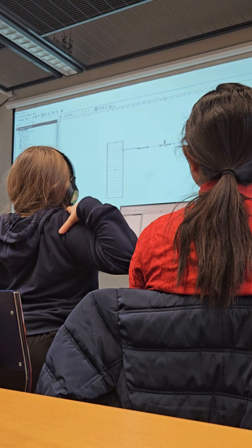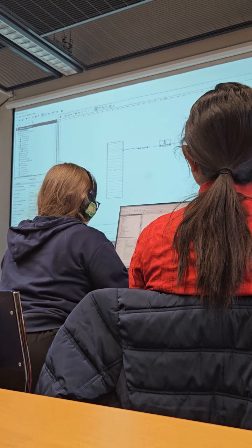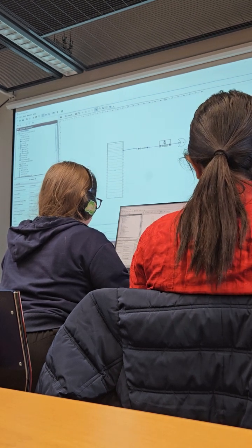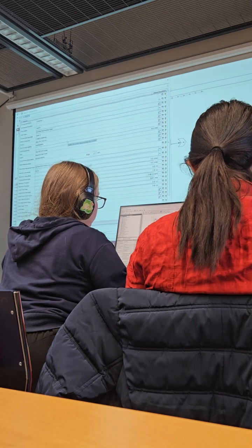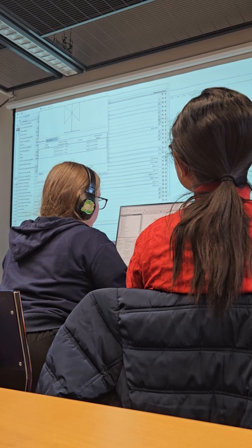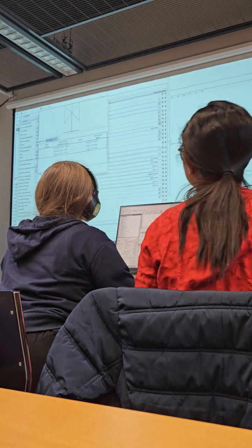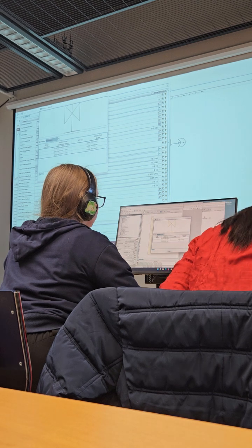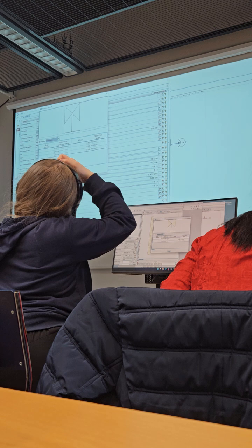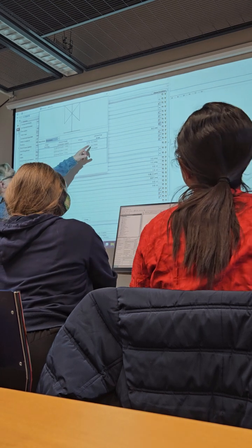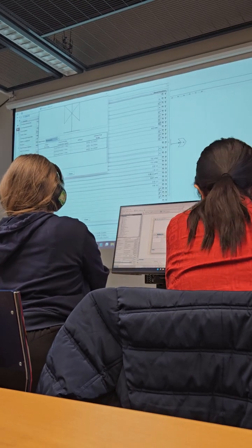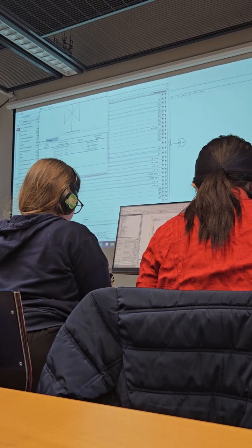But then I have to go to the actual place where I want to put this to work, which is in this valve component. And in the valve component, by double clicking that, you can find it from the very same friction component. Now we can see that something happened because we have chosen this option for the choking flow. Now there are these three in this valve, and everything says no choke. So there is no choke or critical flow checking, so I have to change that.